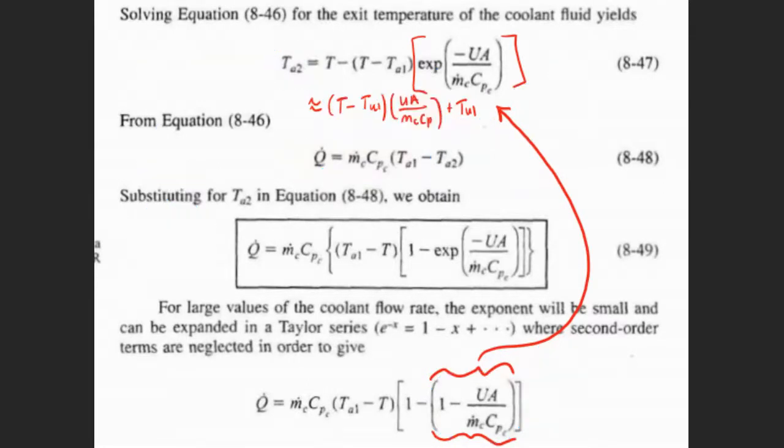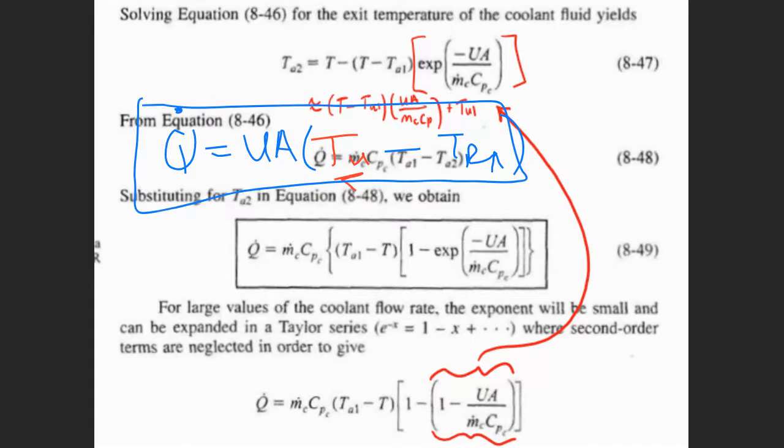And if we then look at our reactor and the rate of heat transfer, we've got a heat transfer coefficient and a temperature difference for heat transfer. The difference is then a constant, because my utility has pretty much a constant temperature, and my reactor has pretty much a constant temperature. So I can therefore use this equation for my heat transfer rate. That is what it boils down to.